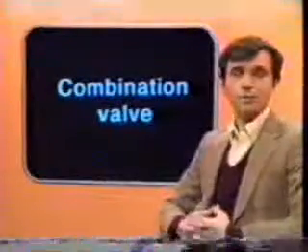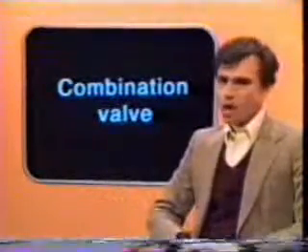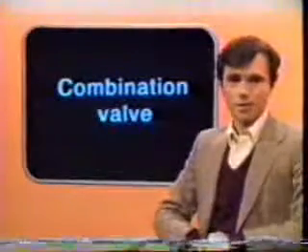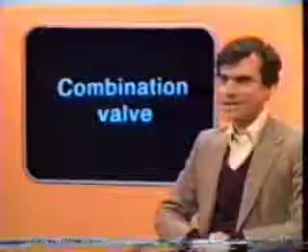There are other valves referred to as combination valves, which are also available for gas lift operations. Information on these and other special purpose valves is available from manufacturers. The type of valve to be used for a given installation will depend on whether the well is to be placed on intermittent or continuous lift. If it is not certain which type of gas lift operation will take place, as in cases where a well's performance is borderline, then valves may be selected which are suitable for both continuous and intermittent lift.